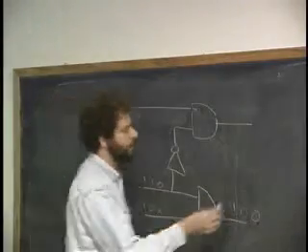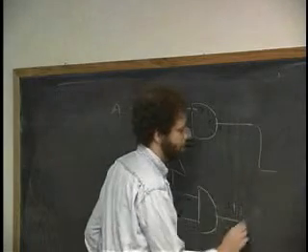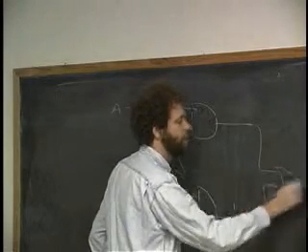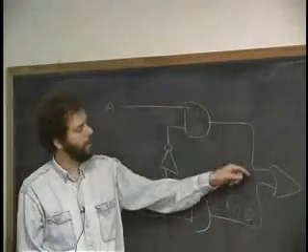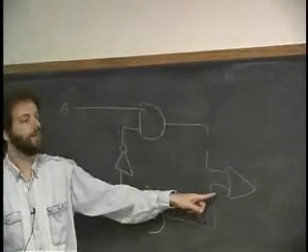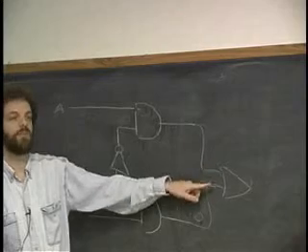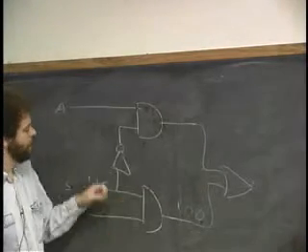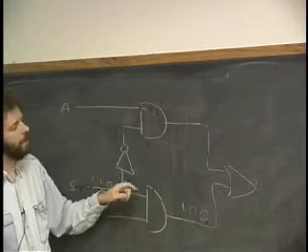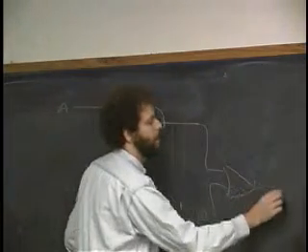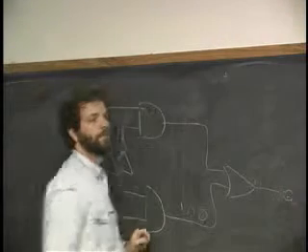And then what we do with these two outputs is we combine them with an OR gate, so whichever one is being gated through, either A or B. And notice only one of them will be gated through and the other one will be at a 0, because when this is low, this is high, and when this is high, this is low, right? Then the output of the selector will come out here, Q.